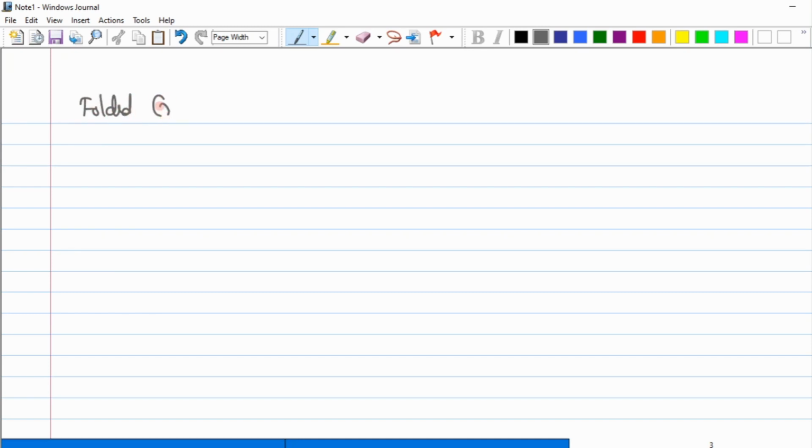So we call this structure the folded cascode, and again there is a further refinement for this name. I'll just write it. What I've done here is that I took the drain resistance RD, and I retained M2 as it is as my NMOS, but rather than connecting an NMOS towards the source of M2, I'm trying to connect a PMOS. Okay, so which terminal do I have to fix here?